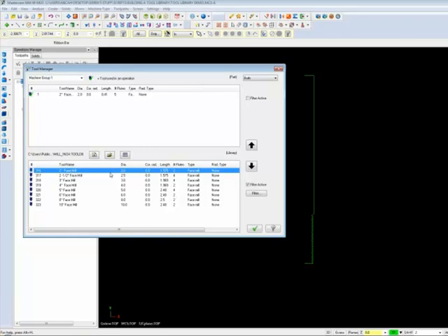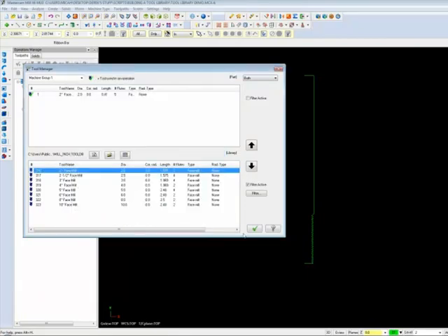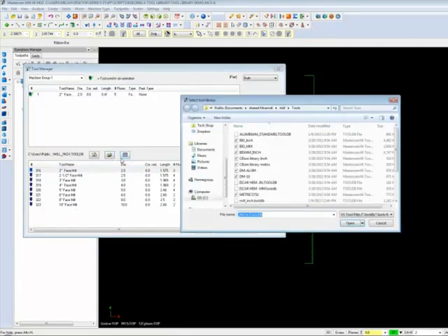So Al, question was answered while we were rambling on there. Another question from Al: if your shell has radii corners, does Mastercam account for this in the step overs? Well, jump in, guys, if I'm not explaining this correctly, but I think the step over is going to be set by the step over percentage that you set in your face mill operation. I don't know if anybody wants to counter me. If not, let's just move on.